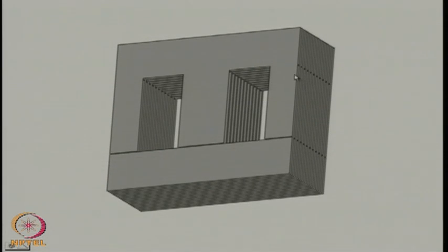Iron being a conducting material, a finite amount of current flows through the core and it causes loss. By laminating, we tend to increase the resistance of the circulating current path, so that the loss is reduced. This is called laminating the transformer core. Almost all practical power frequency transformers are laminated.